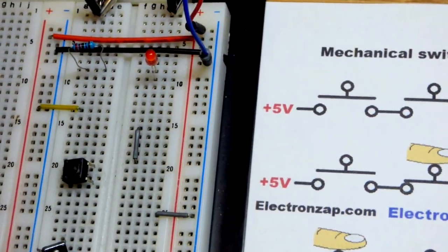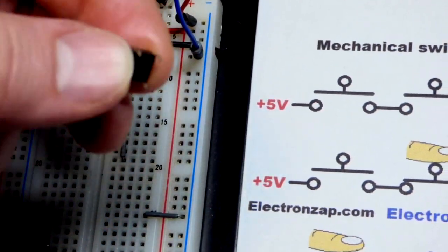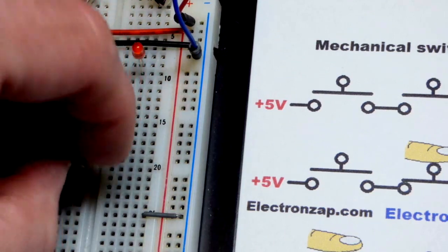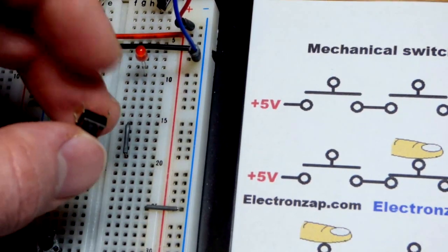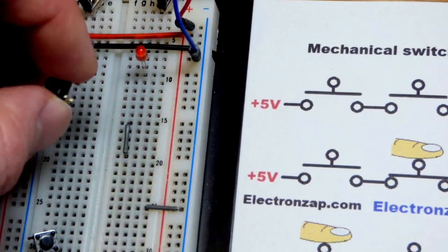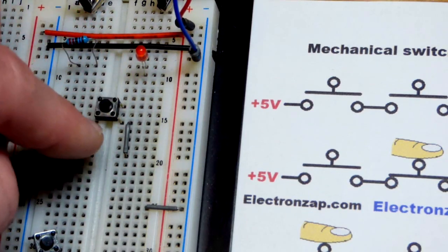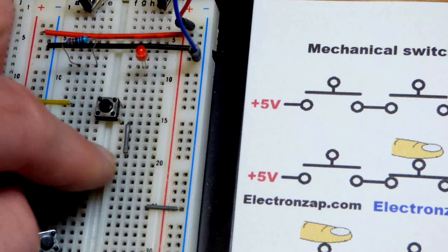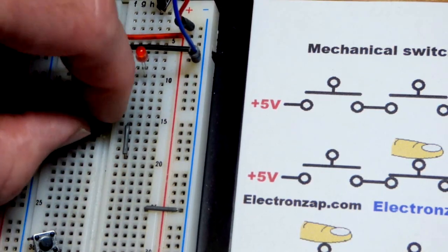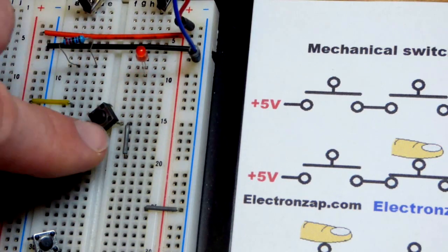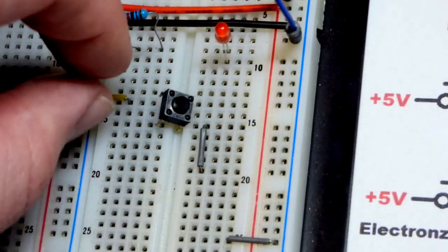So to begin with, we'll come to the first switch. Pretty straightforward. Push button switch, and it's off unless you push the button. You have to insert it into the breadboard the right way though. And so these top two pins are always connected. The bottom two pins are always connected. Luckily, I should call them terminals. Luckily, they fit in the board nicely when you have it the right way when it comes to this gap. Whereas if you try to put it the wrong way on the gap, the pins are too close together to fit into the board. I'll zoom in a little bit.